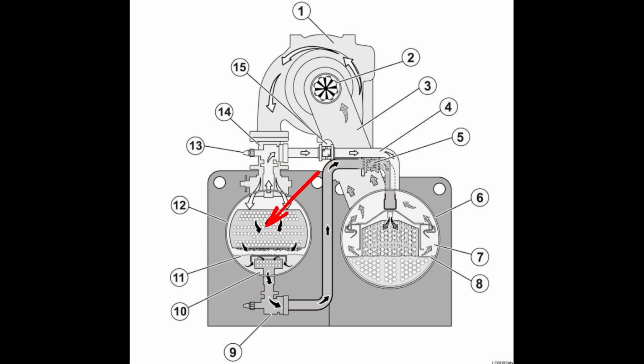We're going to come down an air cooled coil, and the discharge gas goes into the top of the coil, liquid line flows out the bottom. So there's a very natural, just gravity fed type system that's able to move that. And then that oil that does get into the condenser will flow out, and it will make its way to the evaporator, whether it be a water cooled or air cooled design. But then once we get to the evaporator and we've got these flooded or hybrid designs, there's not enough velocity coming off of this oil to get that oil to properly return to our compressor.